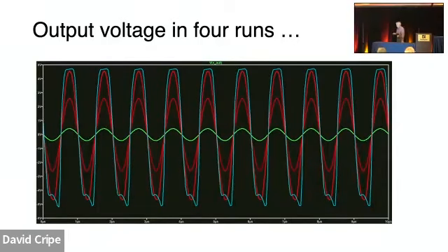And so it's showing them all on the same page. Obviously the one with 0.1 volts drive, 100 millivolts, is that one. There's the next one, the other red one. I don't know if it's called red or not. Looks like we're maintaining fidelity until we get to that last voltage, 1.6. We've got some clipping here, and some waveform abnormality down there. So having seen that, if I wanted to, I could focus in closer, and I might have some criteria I'd set. I might say that waveform's okay, or maybe it's not. It depends on how I'm using this amplifier. But very useful step statement.